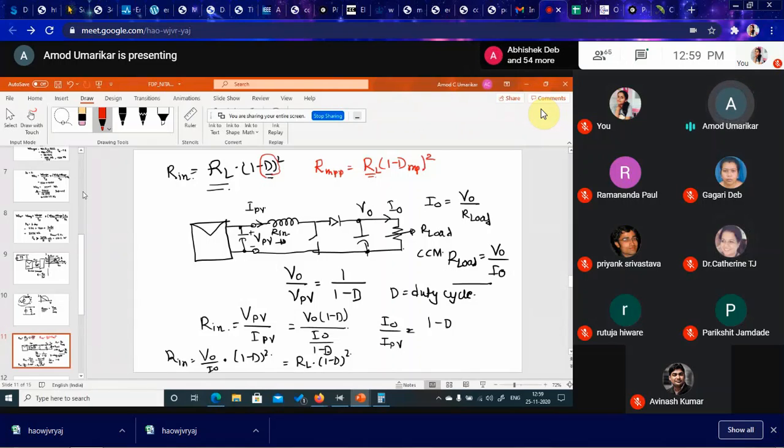I have to illustrate the concept of MPP, how to achieve MPP. The algorithm is another thing. But the algorithm will give a command to something, right, to achieve that. So this DC to DC converter is an actuator. Control is inside the computer or the microcontroller. But who will actuate that? The DC to DC converter. Through what? In a DC to DC converter, it is achieved by duty cycle.